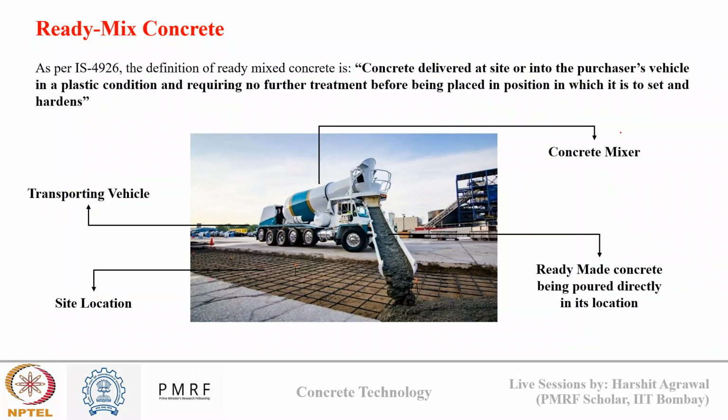So if we go by a standard definition of what ready mix concrete is, as per IS 4926, a ready mix concrete is a concrete delivered at site or into the purchaser's vehicle in a plastic condition. Plastic means flowable condition. And requiring no further treatment before being placed in a position in which it needs to be set and hardened. So in ready mix concrete, this mixing and transportation is done together till the site.